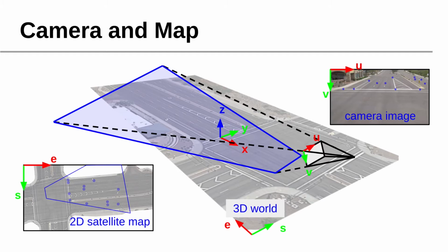The other fundamental problem is the transformation of locations from the 2D image to the 3D world. Here, we set up the 3D world reference frame using the satellite map. Then, we determine the transformation using a set of manually labeled point correspondences. Typically, the ground is close to flat, and the transformation is planar homography between the 2D image and the XOY plane of the 3D world.